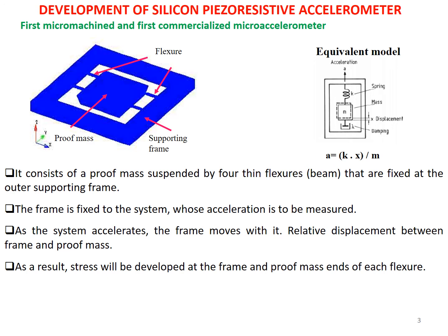So in case of our pressure sensor, what was the moving element? That was the diaphragm, right? And on the diaphragm we have mounted the piezoresistors. So when the diaphragm was moving, those piezoresistors were sensing the stress or strain, and accordingly their resistance was changing, which we were converting into the electrical output with the help of the Wheatstone bridge circuit. So similarly, that type of principle will be exploited for this piezoresistive accelerometer development as well.